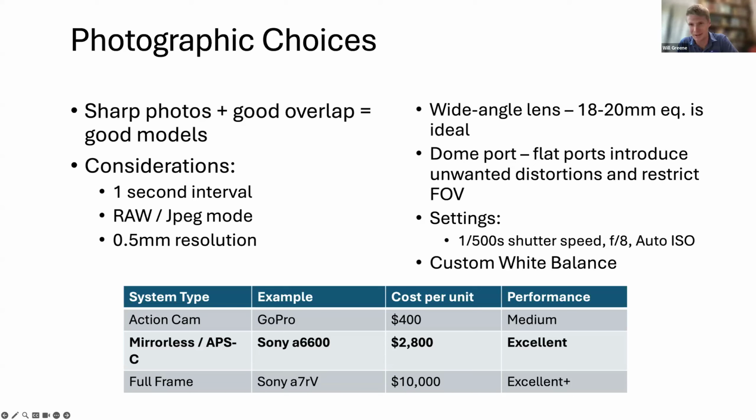What we recommend is that you keep your markers in the same order, going like marker one in the northeast corner of your plot, marker two in the southeast corner, and going around. There's nothing within the script that mandates that, but the reason to do that is because it makes it really easy for you to relocate your plot. At a subsequent time point, if you go down and find one of the markers, then you know what direction to look for the other ones. So it's just for ease of relocation. Yeah, good question though, Matt.